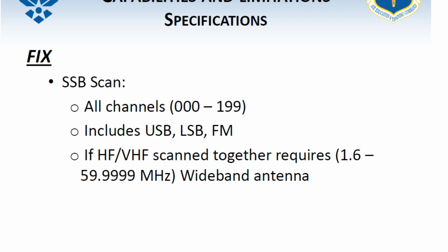You're not going to use an HF antenna for that. Our HF range, if you remember, is 3 to 30 megahertz. If you're using a frequency above 30 megahertz, then you are in the VHF range, so your antenna would not be rated appropriately. If you want to use the full spectrum of the radio, you would want a wideband antenna that can handle those frequencies. Does that make better sense? Yeah, I got it. Thank you.